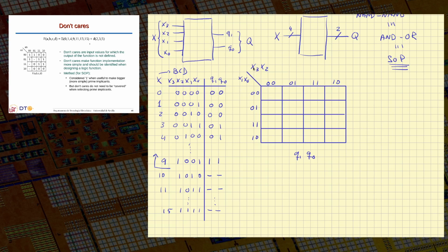So by sorting the variables in this order, the 0, 0, 0, 0 is here, the min term 0 is here, 0, 0, 0, 1 is here, min term 1 is here, and as you see, the min term index is the same as the number represented by the BCD digit. Okay, so it's very good because if you already know the min term position here, these numbers are the number of the min term, but also the number represented by the BCD digit.